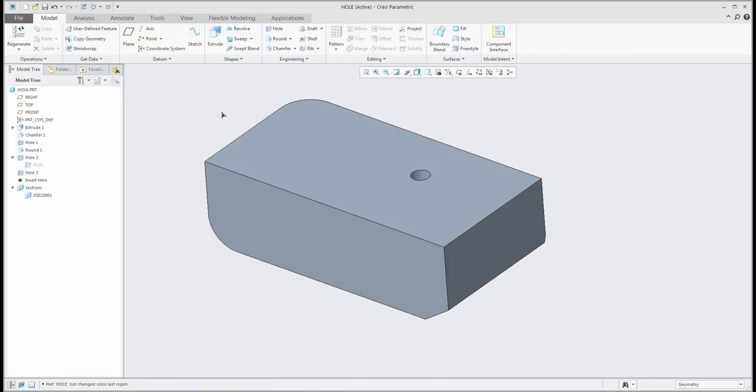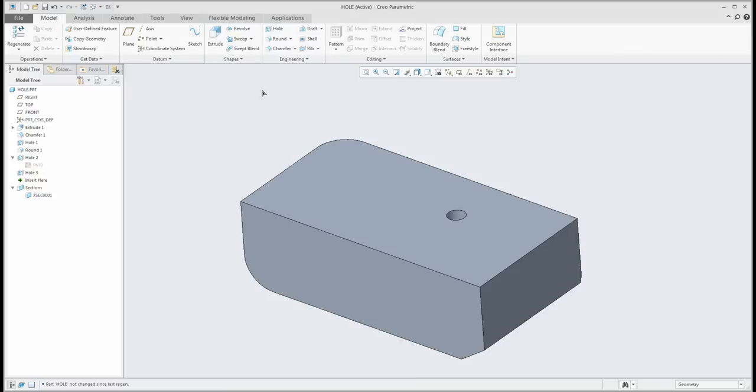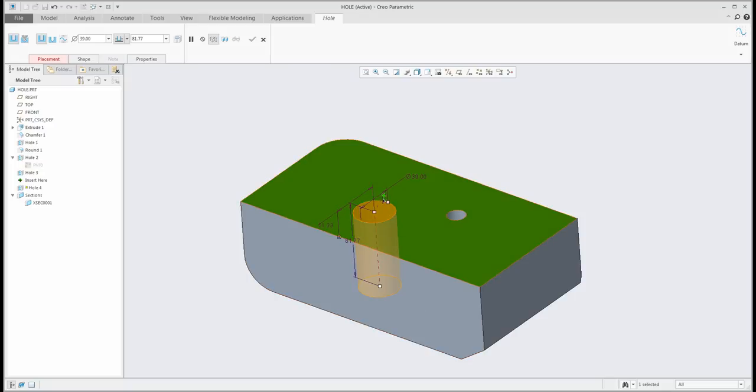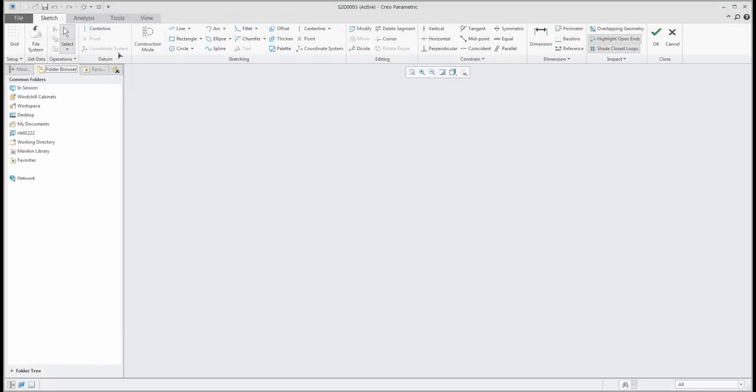Okay. And if you would like to create your custom hole, no problem. Select the hole, select the placement. You can specify the placement here. And then over here is the small icon, use sketch to define drill hole profile. If you select this function, you can jump to the sketch, and the system will allow you to create a center line, and then you can create your custom shape of hole. So for example, I'd like to create a shape like this.